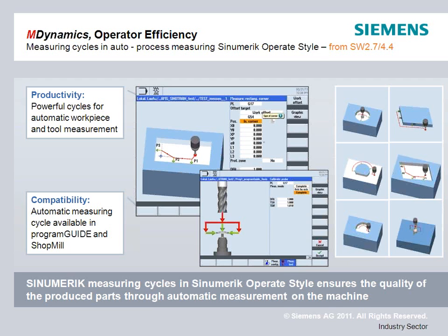If we look at the upper left corner picture, we can also see that if we're trying to locate inside of a pocket and we have some kind of boss or other collision obstacle in the middle, these manual cycles for the operator, all he has to do is load the probe, drive the machine to more or less over the center, pick up some of these graphical sheets and say, well, I want to probe the center of the circle, and I know I have this obstacle that's roughly here, that's roughly this size, that I need to avoid, and let the control do the math for him.